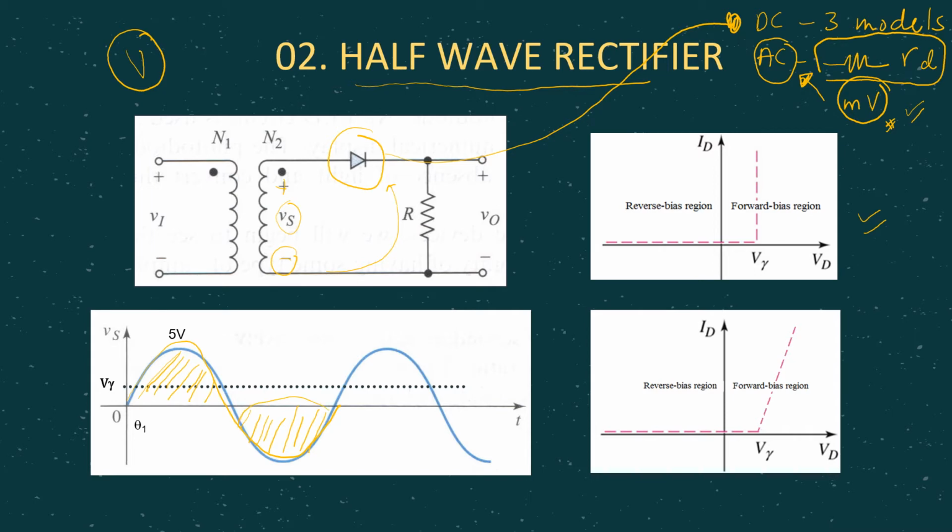then we are dealing with negative voltage, right? So in this case, this Vs is being represented with negative and positive like this. So under this condition, negative is connected to the positive terminal, and positive Vs is connected to the negative terminal. So we know under this condition the diode is off, open circuit, there won't be any current flow.